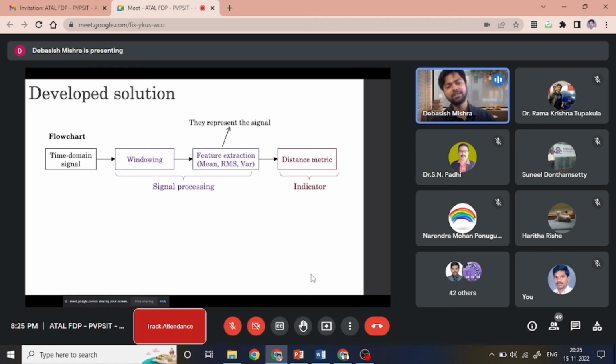As the cutting tool condition degrades, the vibration is intuitively expected to increase because it creates more friction, the rubbing action. There would be less cutting and more rubbing with the deterioration of the cutting tool, and these features represent the vibration signal. We windowed it according to the sampling of the signals. We worked on different window frames, and this running window gives us different features for the vibration and the power signal.